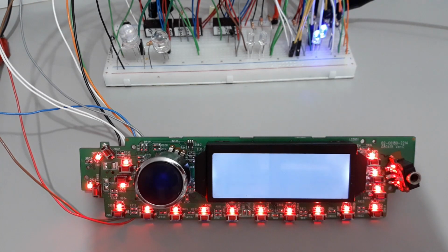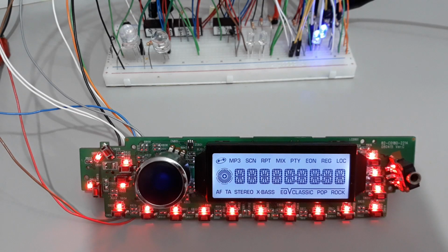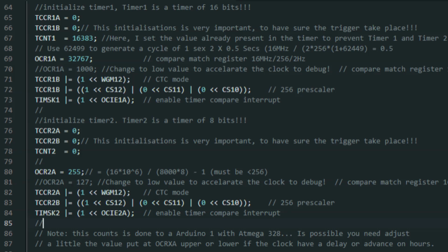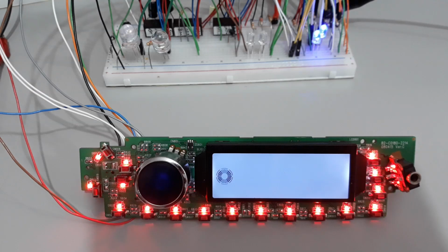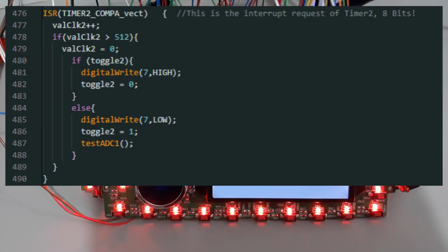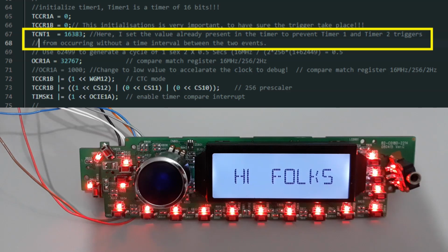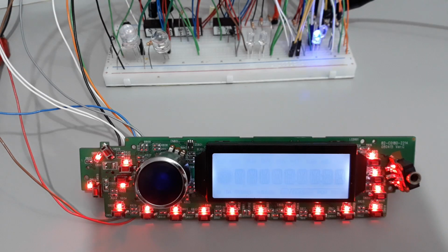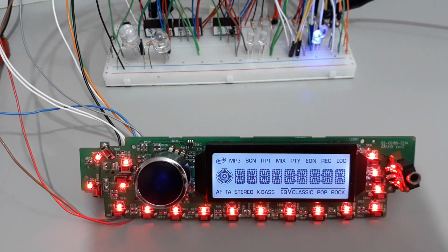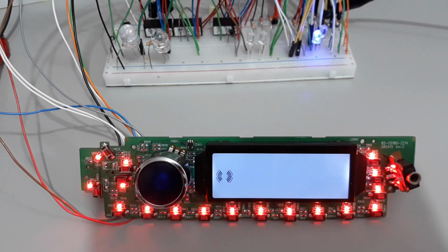To use both keypad buses, two timers are implemented, timer 1 and timer 2, with timer 1 being 16 bits and timer 2 being 8 bits. Therefore, in timer 2, it was necessary to increment a variable so that the two timers would experience the trigger event at close time intervals, but in different phases, in order to leave some slack in the call for the analog pin readings.